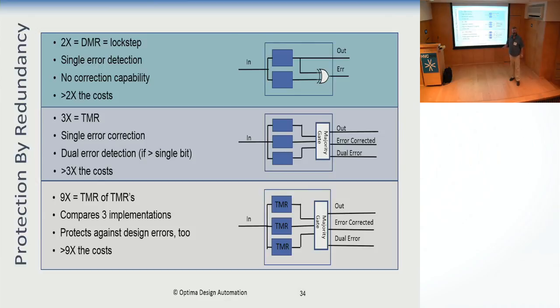So if this system is an optional system and it can be disconnected at will with no bad consequences, wonderful. Then this is good. And if the bit goes up, I disconnect the subsystem and I'm fine. If it's a critical system, I go into the three-way comparison and I get the gate majority that again tells me what to do. So as long as I have a majority and as long as no two get the same error at the same time, I'm not only safe from problems, and not only can I detect the problem, I can also decide what to do about it.